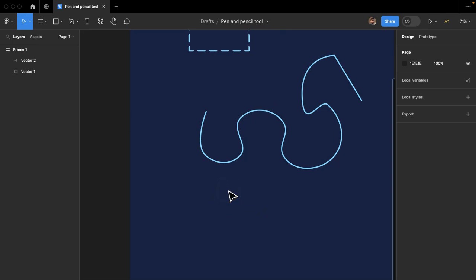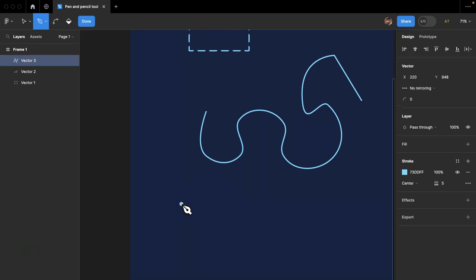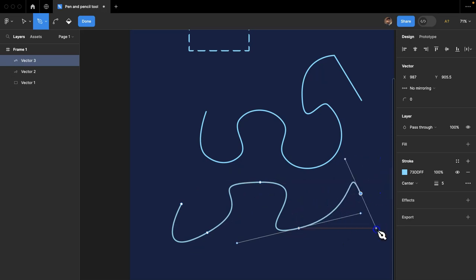But let's say I don't want to draw the shape first and then go into the bend tool and then change the curves. You want to do it simultaneously. So what I will do is, for the pen tool, I'll press the P key. Now I'll click for the first origin. And now I'll not release the button directly. I'll click and hold down, and now I can change the shape however I want. It works that easy. So let's say I want to keep it like this. If I click, I can again change however I want. In any direction, you can make it easily.